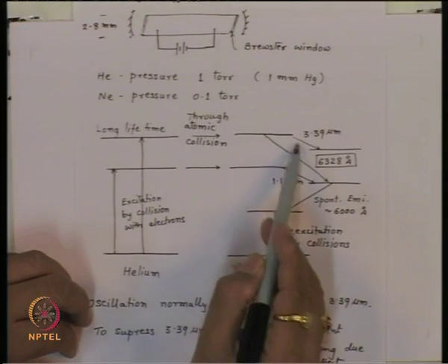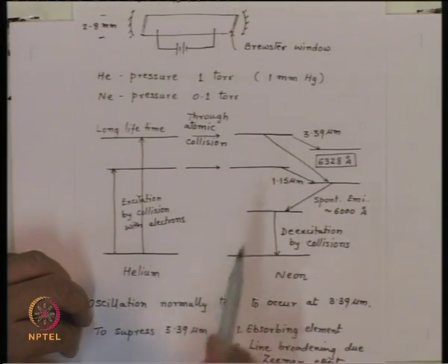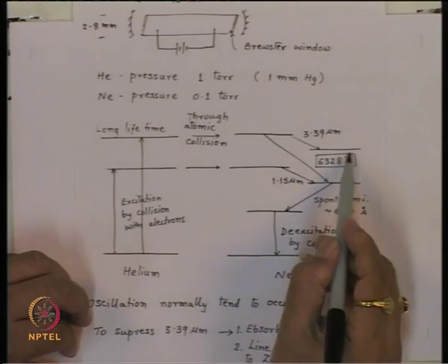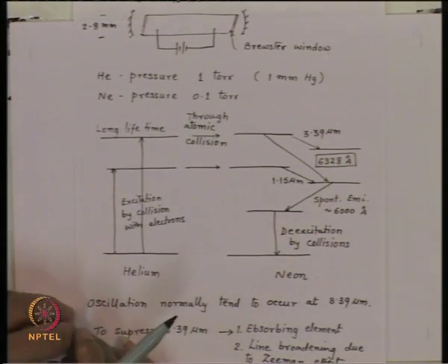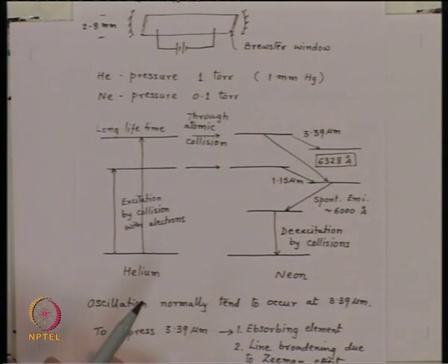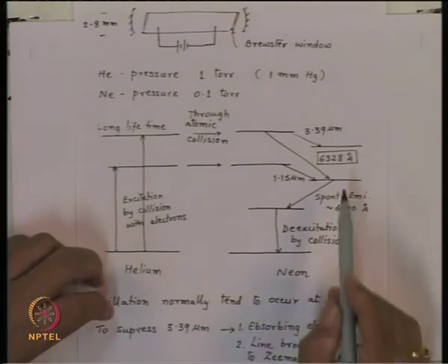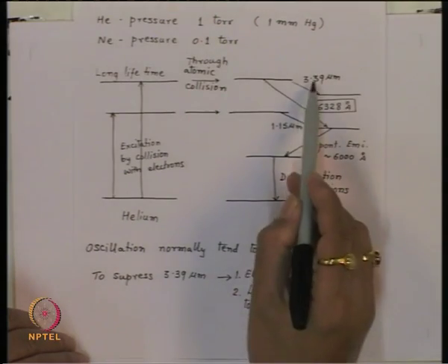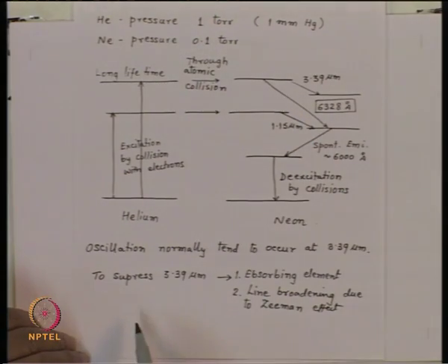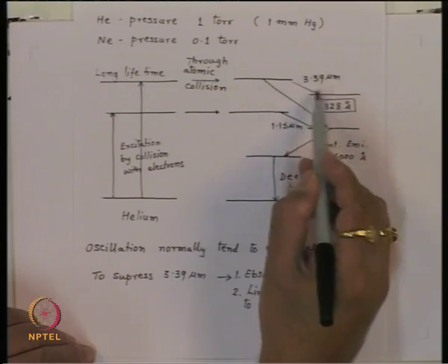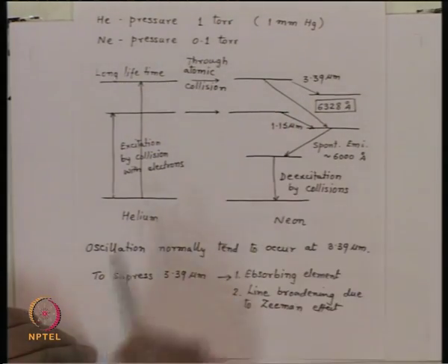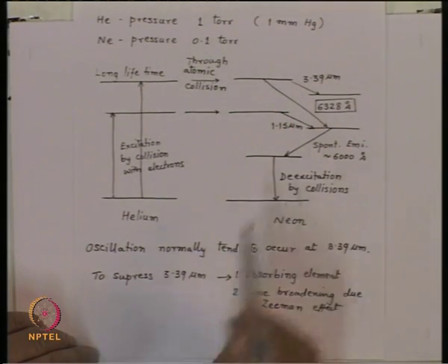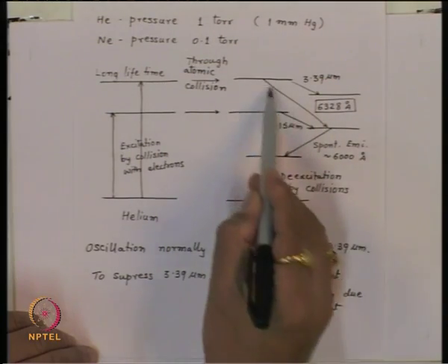These are the wavelengths which will get more easily lased compared to this one in which we are interested. So, what we have to do is create what are called absorbing structures which will absorb these frequencies. So, there is no feedback corresponding to these wavelengths, and this is the wavelength which will get amplified.